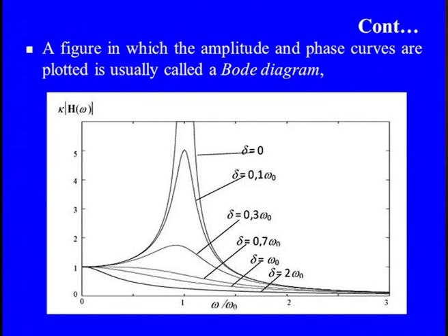So in other words, a huge amplitude is there, and we want to reduce this vibration amplitude. When we adopt the damping factor, it may be material damping, structural damping, viscous damping, or of a mixed, complex nature. Then the vibration excitation can be brought down by adopting different values of damper. So we have delta 0.1 omega 0, then 0.3, 0.7, or if delta equals omega 0, the critically damped one, the effective utilization is there.